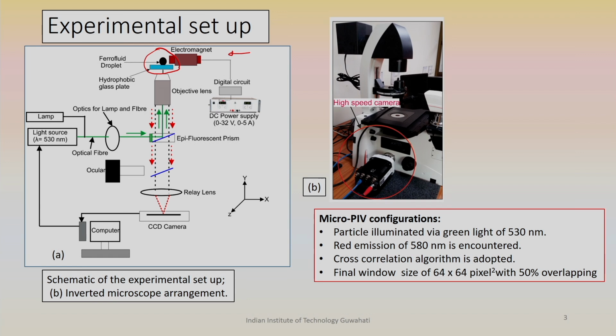internally. Within the droplet volume, a flow field is developed because of the movement of the nanoparticles. Our objective is not to capture the ferrodynamics in detail, but because of the movement of the iron nanoparticles towards the magnet, a flow field will be developed inside the droplet domain, and our objective is to capture the flow produced both qualitatively as well as quantitatively.